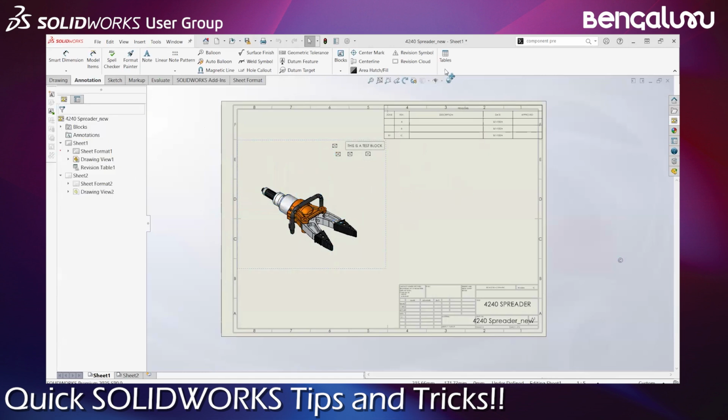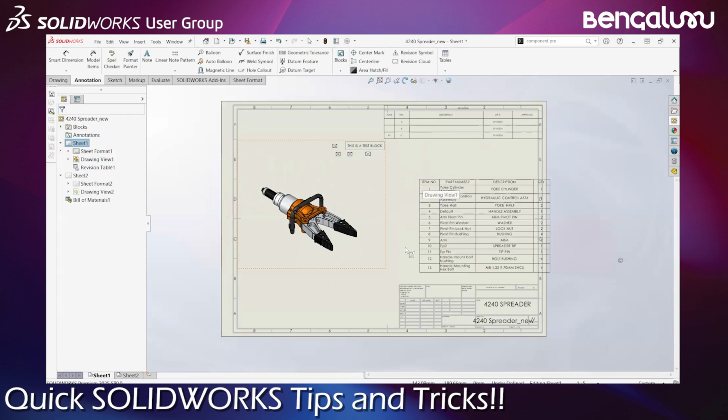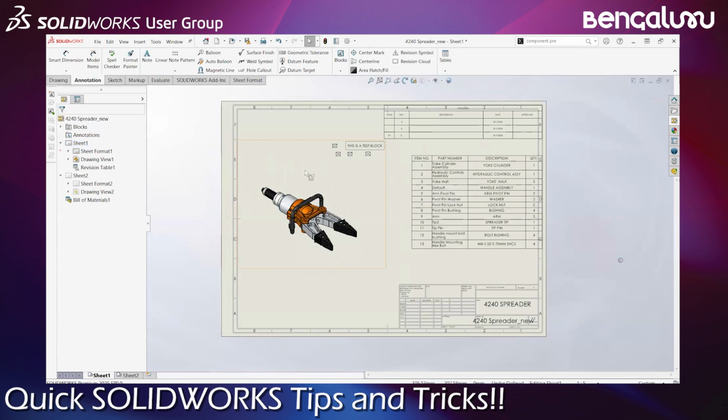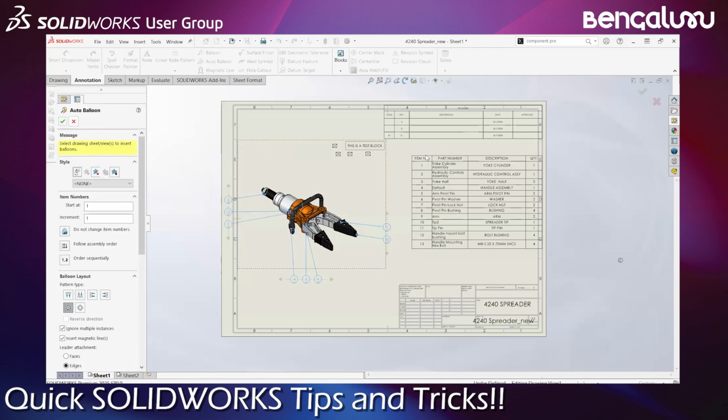So now I'll go ahead and select the bill of materials and select this particular view, and I say top level only, and then I add a BOM. Then the typical workflow is I select the view and do the auto balloon. So balloons have been added. Now I go ahead and filter this BOM. When you hover over the BOM, you should be able to see that drop down that comes up just beside the column name.